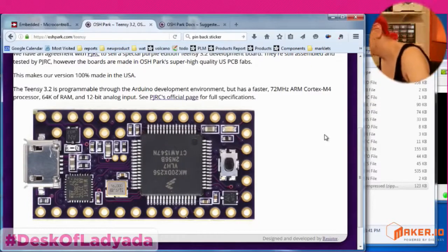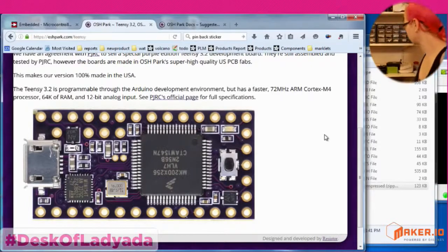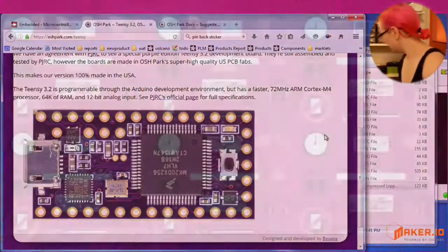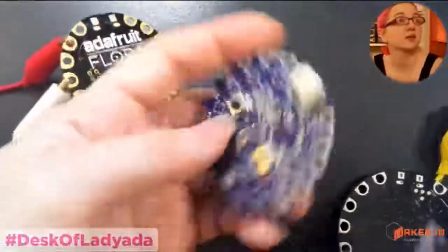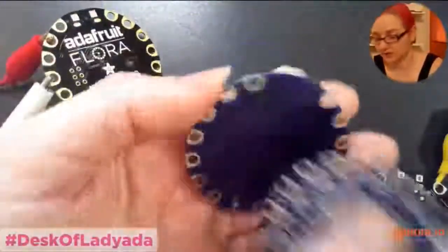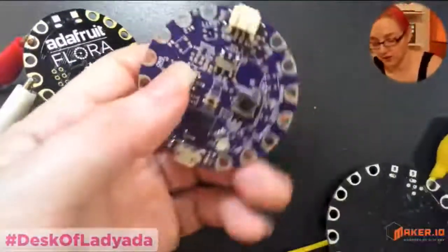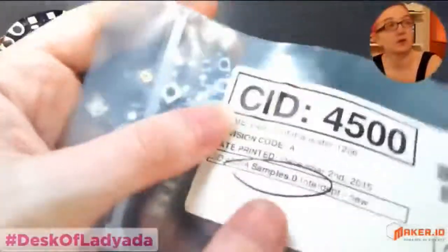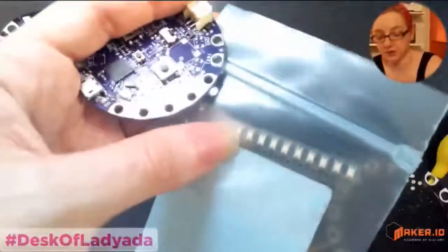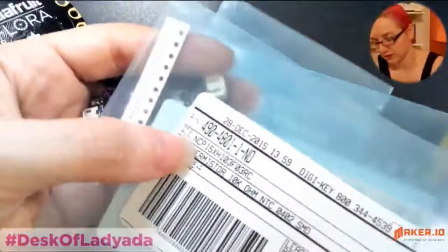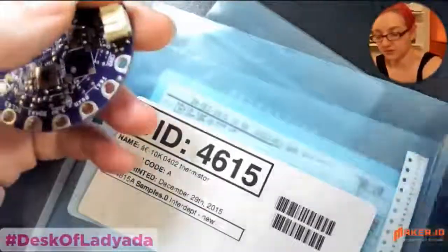Okay, and then let's see if I have a prototype. So what you'll get when you're done, can you go to the overhead? Is a PCB like this. Purple PCB. This is not from OSH Park. That was the super swift one. But you'll get these purple PCBs, and you can get started, and then you've ordered all your components. So you've ordered little strips of parts from, for example, DigiKey. I got these resistor arrays and some thermistors, part NCP15X103F. So all these parts come on little strips of tape.